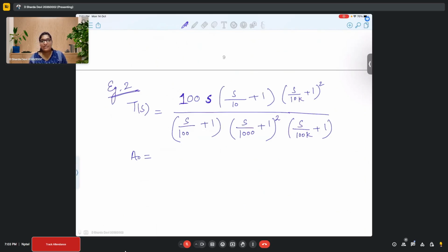The moment you see the transfer function, be it in any form, try to bring it to this particular style of form. When you bring your transfer function to this form, it is very easy to analyze things. Like you can pick your poles and zeros just by looking at the transfer function, and you can also comment on the DC gain. Now, other than this, let's say if I would have written my transfer function as 100.